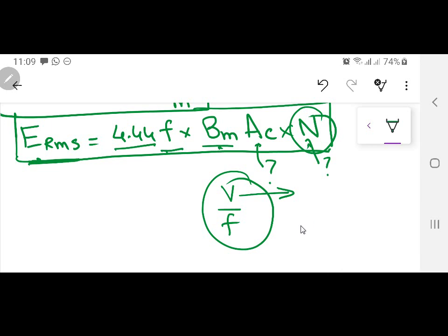Now, on the high voltage winding, which is on the outer part, if you give more than the rated voltage, the insulation will not withstand, and between the two turns, there will be a spark, which means the dielectric strength of that insulation cannot withstand that voltage. So if a transformer is designed for 200 volt or 220 volt, it has to be kept at that voltage. You can give less.